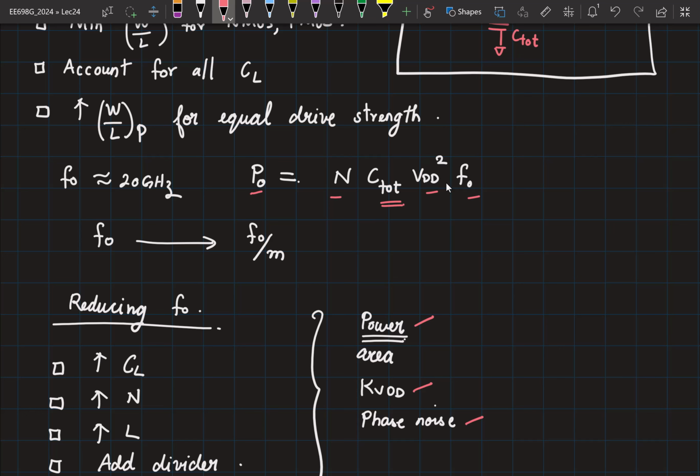Do you think this will be accurate, or is it likely to? What is the error you expect? Like, what is the reason for the error? All of that gets accounted here. Changes. Let's assume VDD is constant, right? Basically, CGs and CDs and all are dependent on the bias of the thing, right? Correct. But we want to know what is the C total on an average during the entire rise.